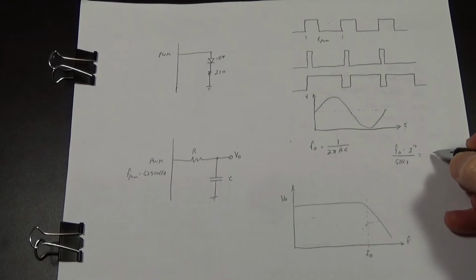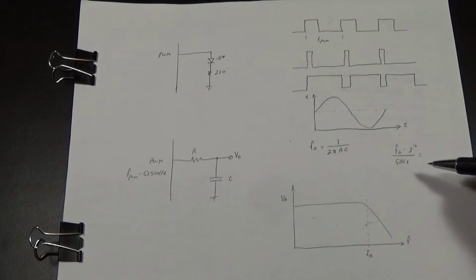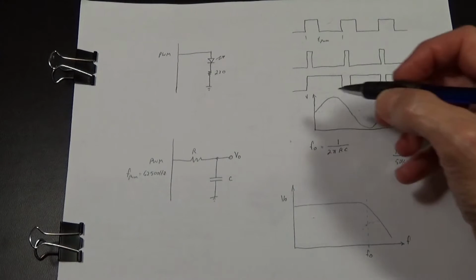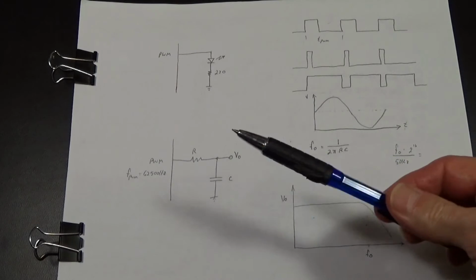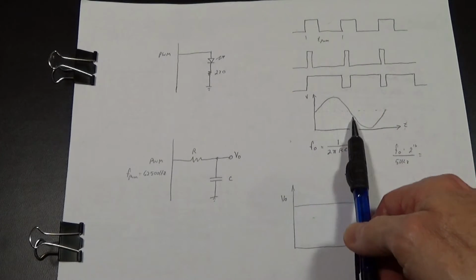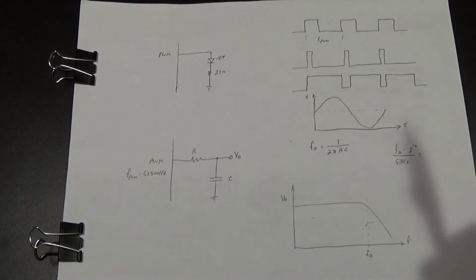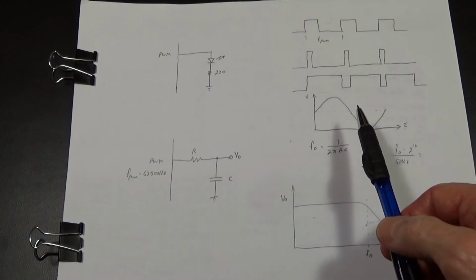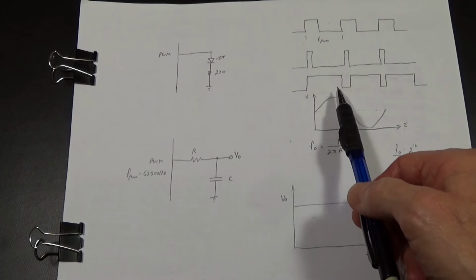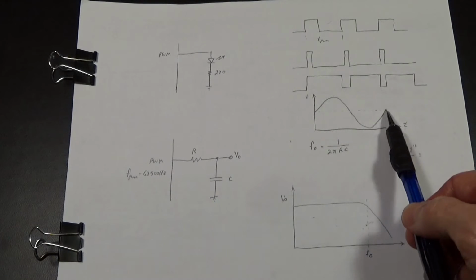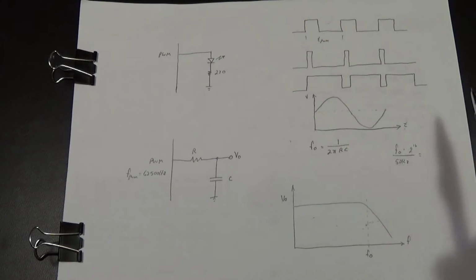That will give you the value that you increment your 16-bit counter by every 20 microseconds, or 1 over 50 kilohertz. What that does is pick only certain values along the phase of this sine wave. Then we put that into the PWM, and it produces a voltage at that point, then a voltage here, and another one over here, and so on and so forth. It does this repeatedly, and that will give you the frequency that you want.